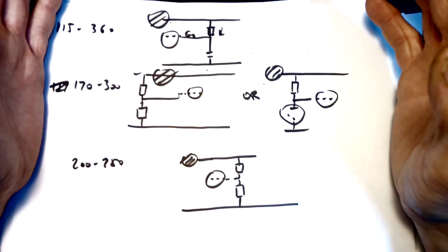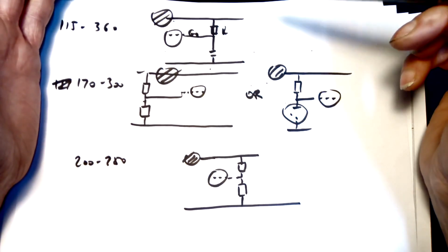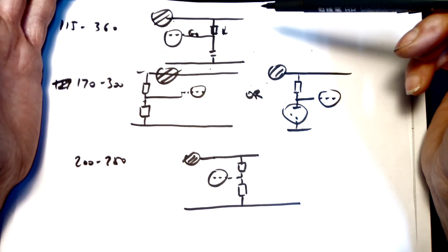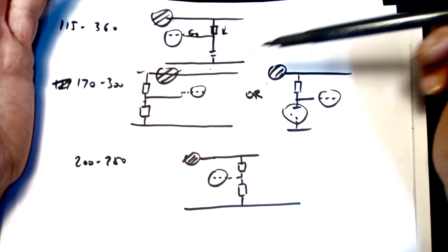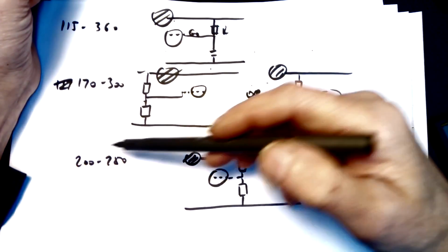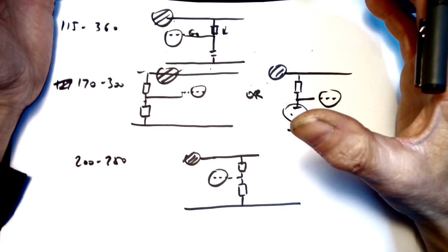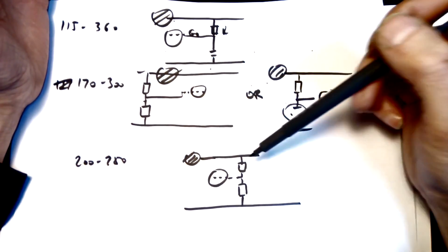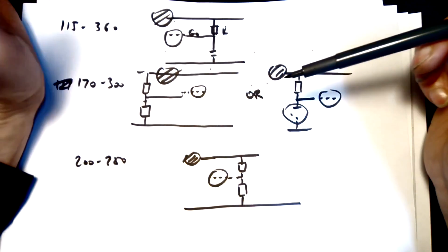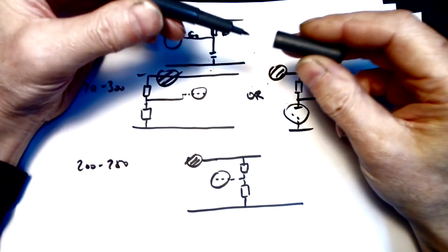For the middle range, let's say, we have to use a voltage divider from this side, or try to support it with a neon lamp. And if the range is definitely smaller, we can just use the voltage divider from the output side, and it will be the best from different points of view.